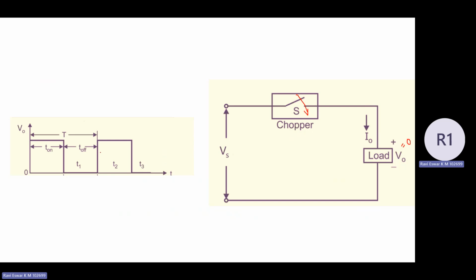We already saw the definition of power electronics. It is the application of power semiconductors to control and convert power efficiently. What is motivated here is efficient power conversion, where the semiconductor is operated in a manner of switching. When it is fully on, the current is there in the switch, but the voltage is ideally equal to 0.